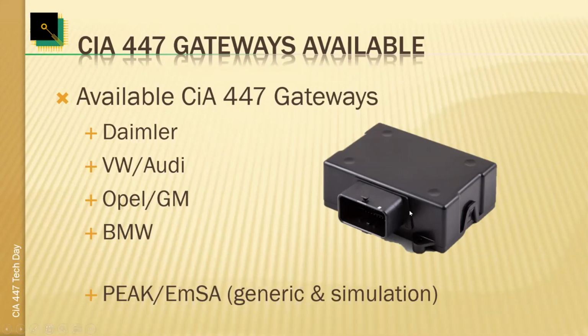There's no size comparison here, but this is, well, bad example, but the only thing that currently comes to mind is a box of cigarettes. So this is maybe the size of 2 boxes of cigarettes, the small ones. And it has only one connector. This is not the specified CiA 447 connector, because on here there are a lot of discrete I/O additional pins, and there are additional CAN and LIN interfaces. So this can be programmed quite flexibly to support a number of different vehicles.